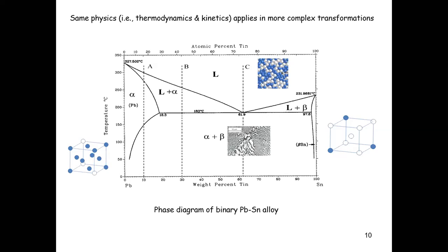We don't want this to happen, but occasionally we drop our phone on the table or on the floor. When you drop the phone, it undergoes a huge impact force. Your screen is going to crack, but the chips inside the phone also feel this impact force, and you don't want the joint to be broken under it. Otherwise, the whole thing is not going to work. So we want the solder material to be highly conductive, but also mechanically stable and resistant to these impact forces. So we have to do quite a good job engineering the microstructure to achieve this.